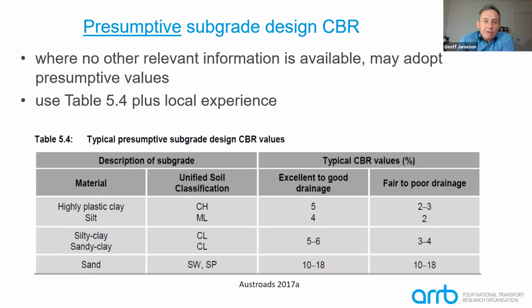Another means of estimating the subgrade CBR, instead of doing some laboratory soaked CBRs or some in situ CBR testing, is to use some presumptive values. This commonly plays a very important role in coming up with the design CBR.